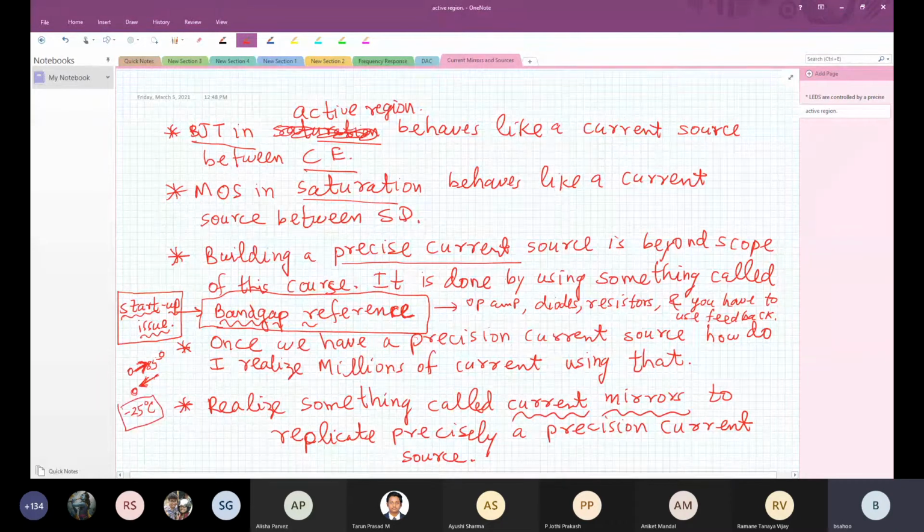Then Motorola got back to us, and it took us quite some time to go to the lab. We went to the lab and did this temperature cycling in the lab. You have temp chambers in which you can do the temperature cycling. We replicated this happening. Then we pinpointed which part of the circuit was causing the problem. From there, we found out it was actually a simple current source that was giving this problem. And then we had to come up with a fix. We did a lot of simulations and convinced Motorola.